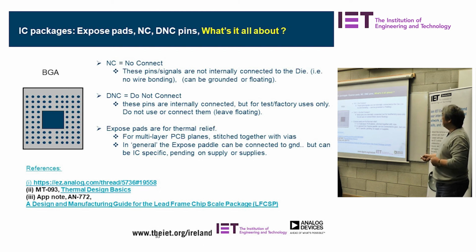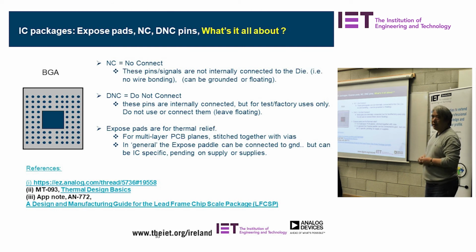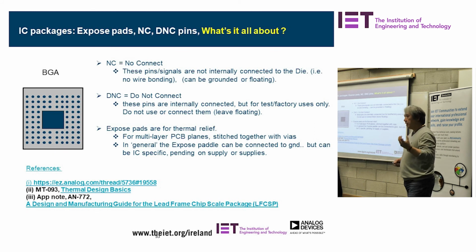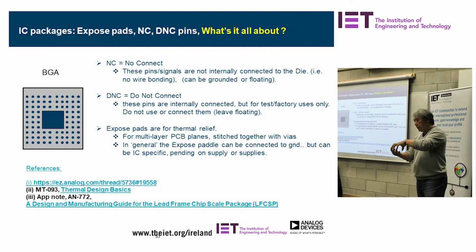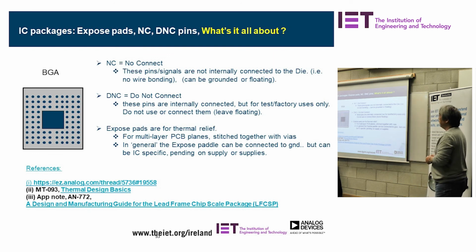And then you see a lot of technology now has exposed pads. A lot of people ask me what to do with the exposed pads. An exposed pad is like a heat sink. It actually helps with thermal relief, and we have a couple of papers on this, on how best to use it. Rather than connecting a big bulk of solder, it's best to connect through wires, and the wires are connected to each plane to distribute the heat.